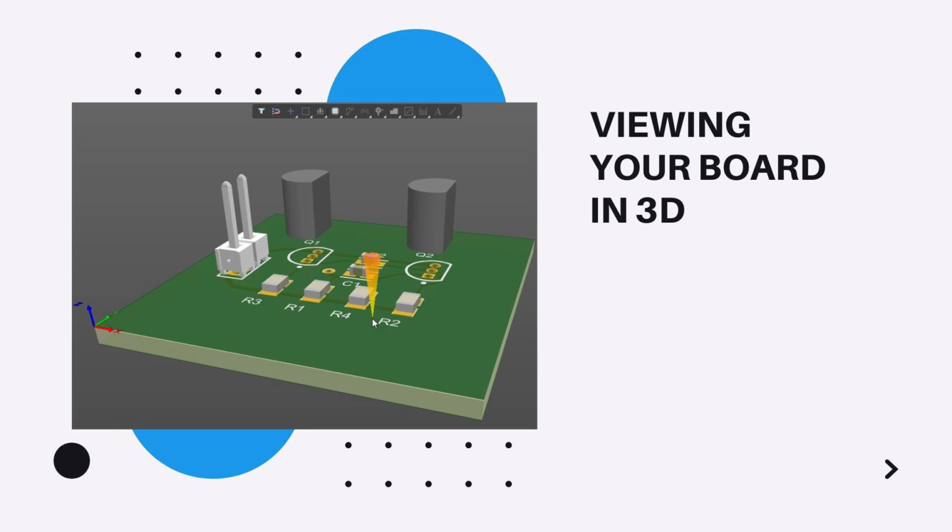Now make sure the PCB editor actually requires a graphics card that supports DirectX. Now refer to the system requirements page for more details. You can fluidly zoom the view, rotate it, and even travel inside the board using the following controls. In zooming, press Control, right-click, hold and drag, or Control mouse wheel, or the Page Up or Down keys. In panning, right-click, hold and drag, or use the standard Windows mouse wheel controls.